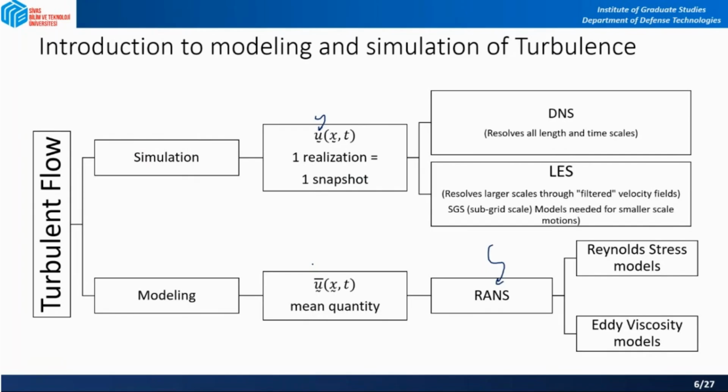commercial codes fool you while you are solving, for example, unsteady flow. That unsteady flow in RANS models, in Reynolds-averaged Navier-Stokes models, is not instantaneous type of data. Those are also averaged. We will talk about it because in the RANS models, if you remember the Reynolds-averaged Navier-Stokes equations, there is no information on the instantaneous eddies. So you cannot solve for the instantaneous flow.